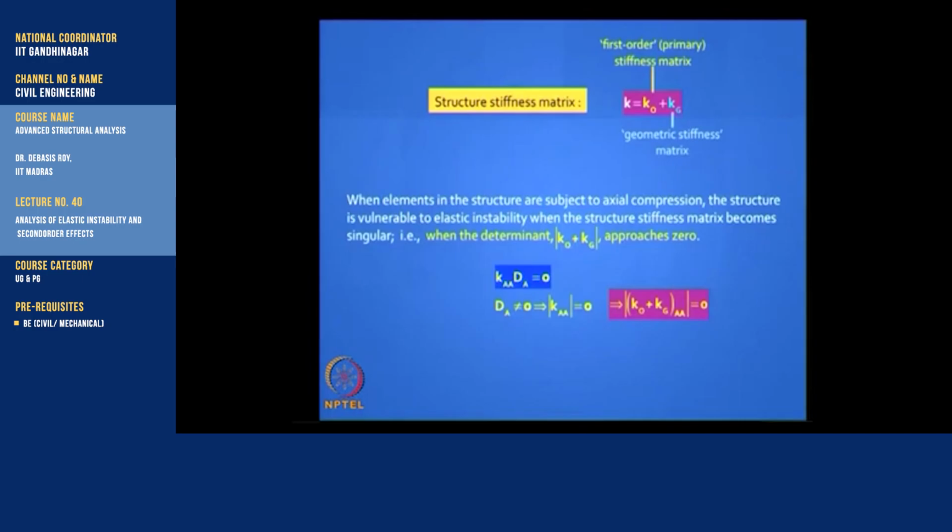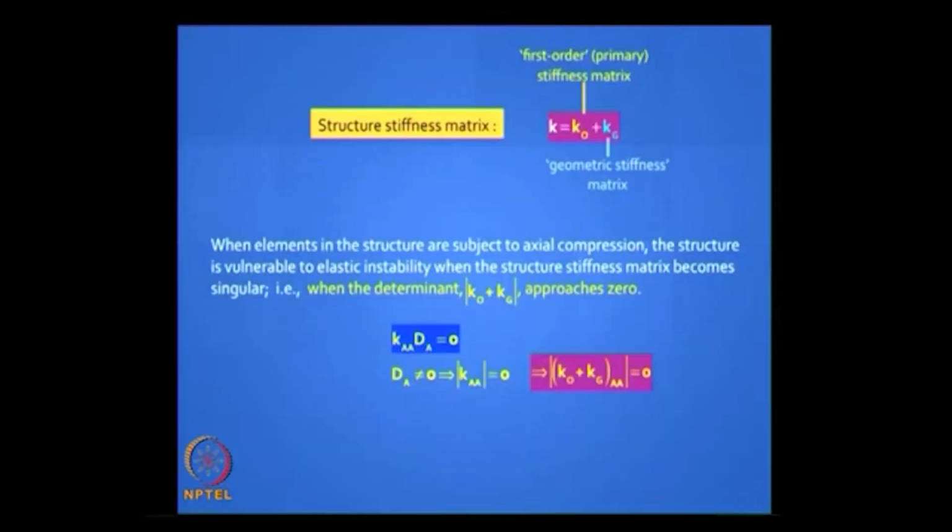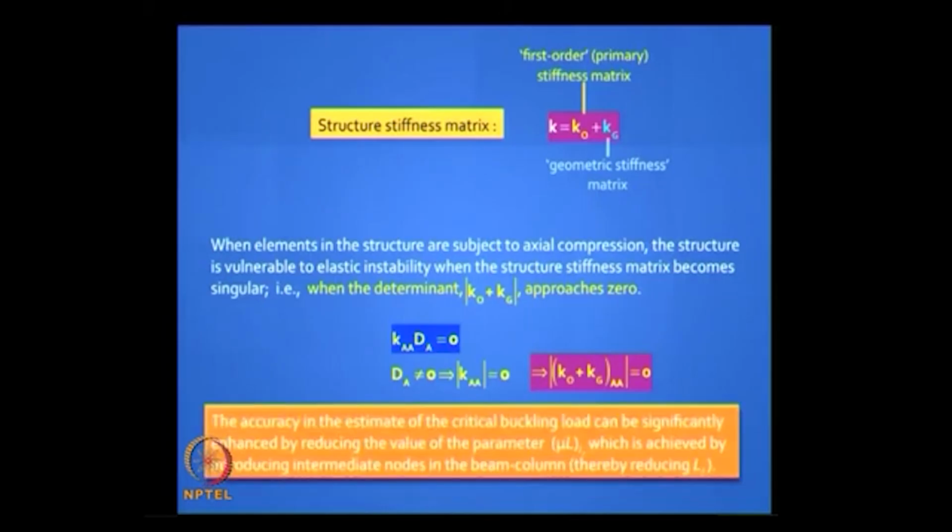Is it clear? So supposing you had distributed loads, do not worry about them, convert them to equivalent concentrated loads, let there be only axial forces in the structure, okay, initially. If you had what is known as pre-buckling moments, it is okay, you keep them aside for the time being, because they do not really affect your critical buckling capacity, because you have studied earlier that asymptotically you will hit that value, right. Of course probably your structure will collapse well before that, because you have other non-linearities coming into play.